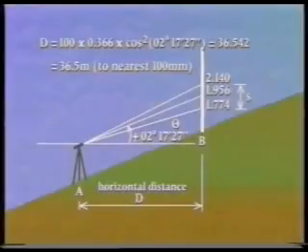Remember, any reading error is multiplied by the K value of 100, so even a misreading of only 1 millimeter will cause a distance error of 100 millimeters. For this reason, any horizontal distances should only be quoted to the nearest 100 millimeters.